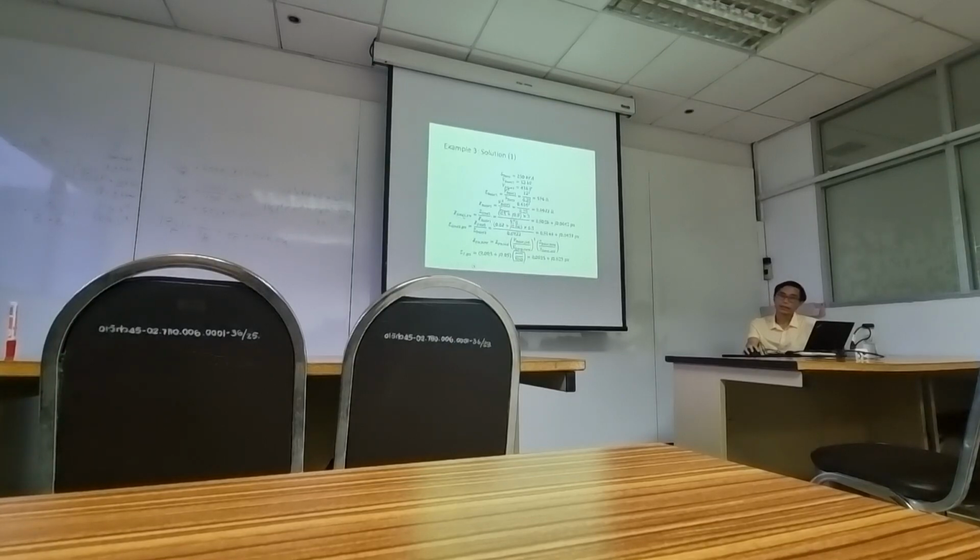Then this is the line impedance. Line 1 is on the high voltage or medium voltage side. Line 2 is on the low voltage side. Remember that this is ohms per kilometer, so we have to multiply by 3 kilometers, or multiply by 5 kilometers.